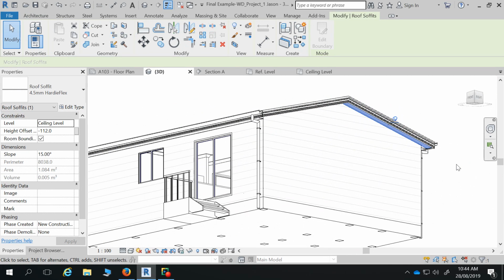Right. And that's where I suppose you've got to start thinking, especially for the next drawing, how much of this model am I actually modelling to get it to council and get it built? Because sometimes you have to ask yourself that question, because you might think, I've just done 2 hours of modelling stuff and no one except me is ever going to see it. So unless someone's going to use the soffit in Revit to take off how much soffit lining there is, and you're not seeing it in any of your views, then it's a waste of your time.